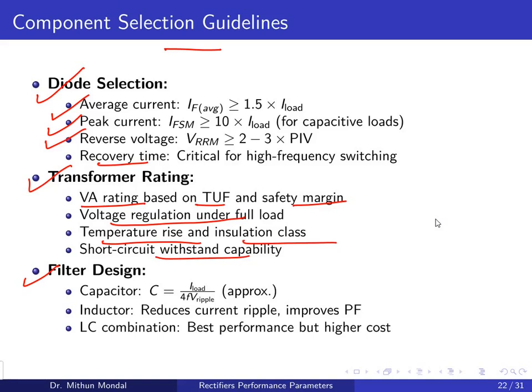We need to calculate the value of the capacitor that is required for proper filter design. The inductor will reduce the current ripple, which will improve the power factor. The LC combination will have the best performance, but will have the higher cost.